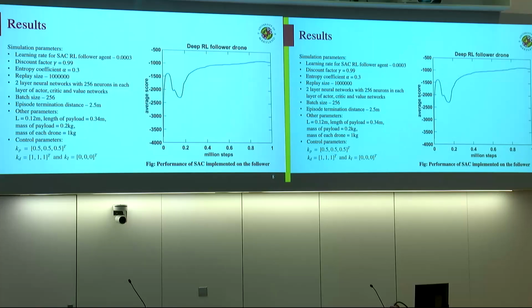One more point I wanted to mention is that I'm using PID control for the leader and RL for the follower. I could have said, let's use RL for both the robots. But I didn't do that because we know that machine learning algorithms and AI-based schemes are dynamics free, but they're data intensive. If the data is wrong, they'll not behave properly. There are no stability guarantees. But the traditional control approaches are perfect, but they are heavily dynamics dependent. So to get a good trade-off and a good hybrid between the two, I chose one robot to be the leader with PID and the other to be RL.